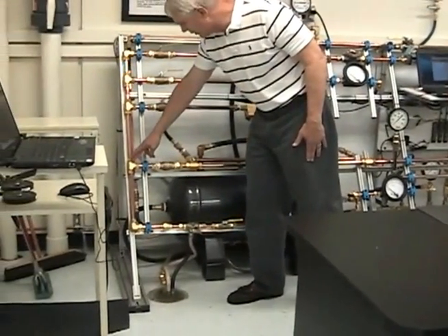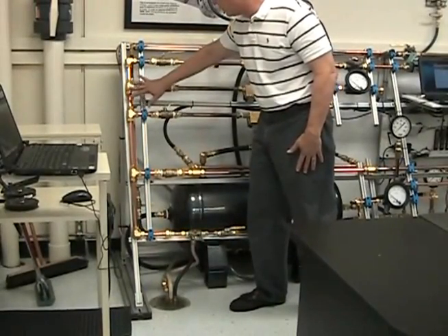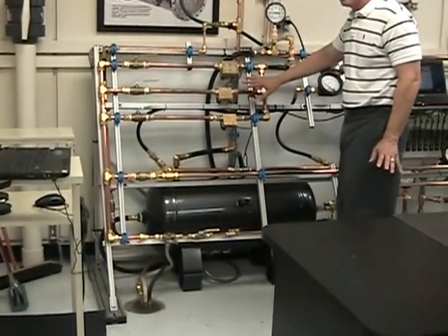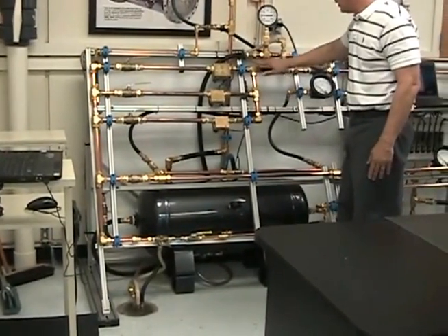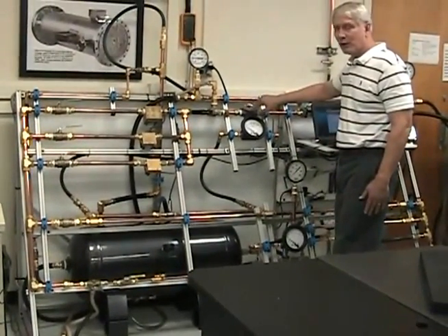Then we'll come out at the other end here, and it will go up, and depending on how you set the valves up over here, it'll go into one of these three pipes where it'll pass through a flow meter, and I'll go over this in more detail in a minute. And then it will come out and it'll go through this pipe. There's a sight gauge right here so you can see if you have flow.